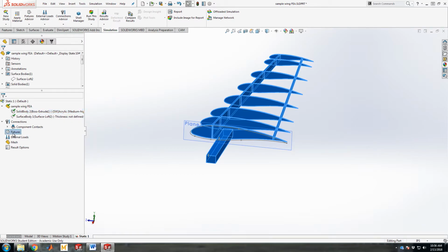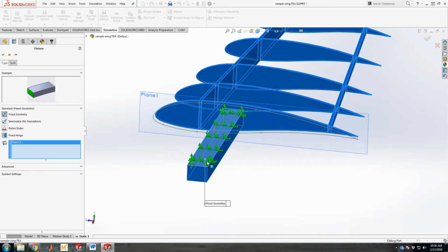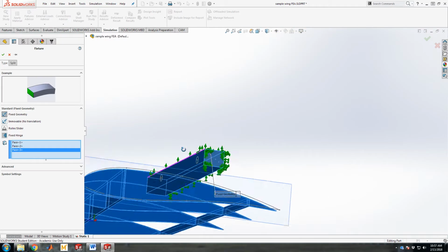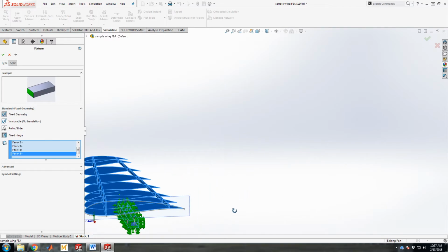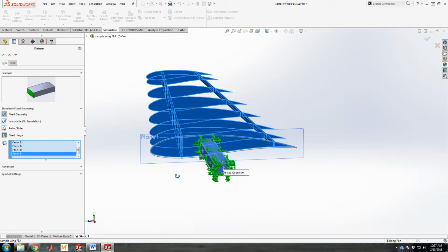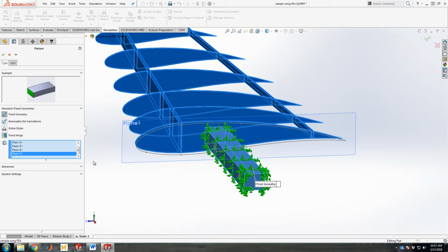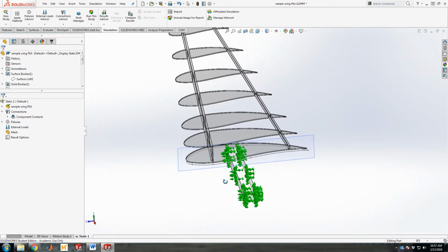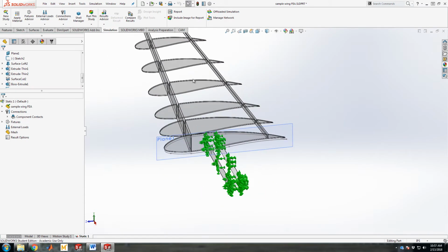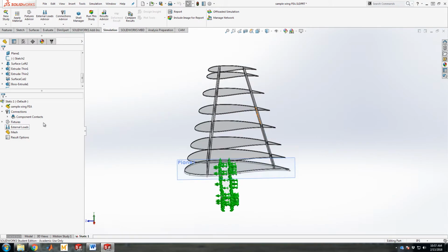So anyway, fixtures. Let's apply some fixed geometry. These are basically one of the types of boundary conditions you apply to finite element analysis. This is modeling like if you had just glued that stick into a mount permanently. Those surfaces mathematically will not move. There will be zero deflection on every one of the nodes forever and ever. Cool. That end condition in reality probably doesn't exist, with the exception of bonding it into a perfectly machined hole.